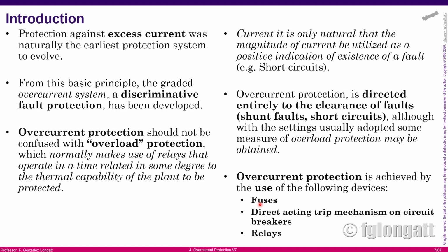For instance, in low voltage, you can find those small blocks that we call direct acting trip mechanisms inside the circuit breaker. And of course, when you move to higher voltages, the overcurrent protection functionality must go outside the circuit breaker.